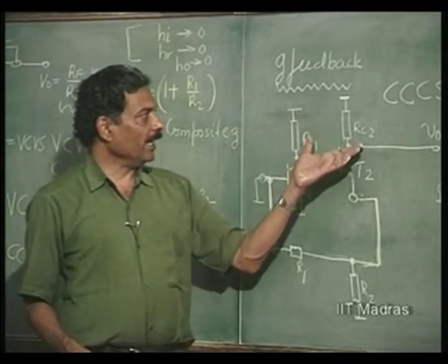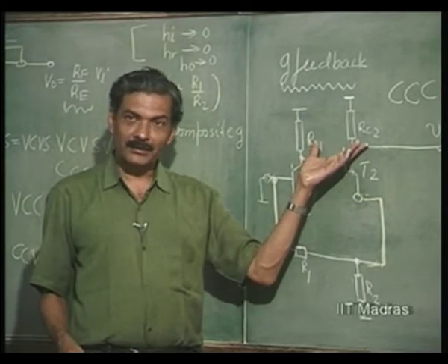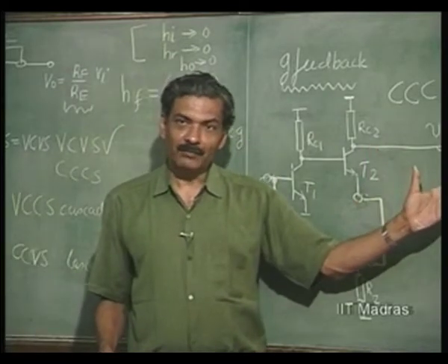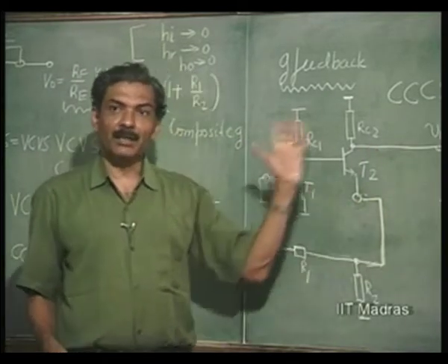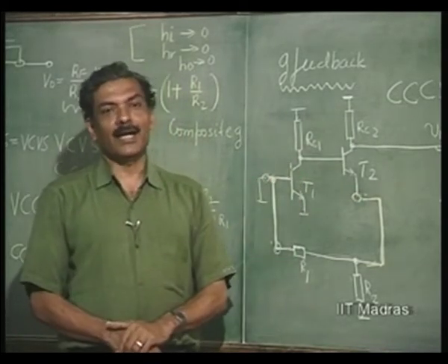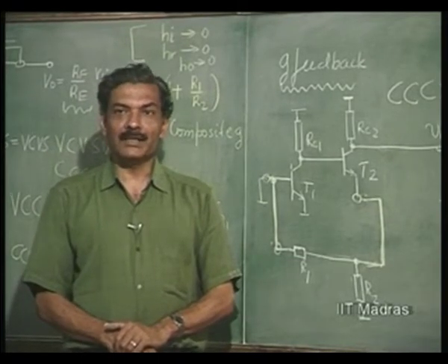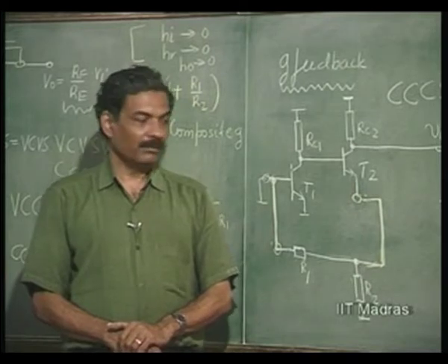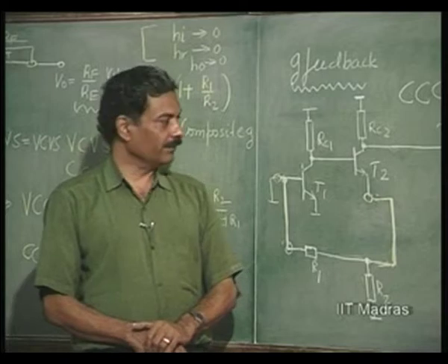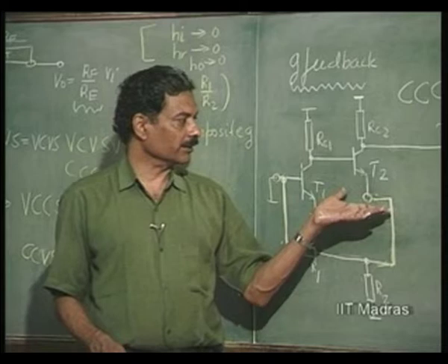This pair gives you problems if the loop gain is pretty high, but if you add one more stage of amplifier, make it a triple instead of a pair, then definitely it is rare that such a circuit straight away works without what is called frequency compensation, right. We will discuss these effects of high frequency and effect of delay in the individual stages at a later point. That is also very important.